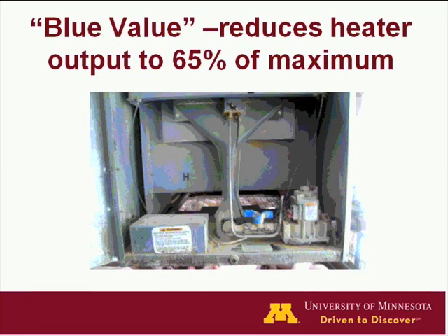It's generally accepted in pig facilities that most of the heaters are oversized. Most of the direct-fired heaters have a capacity of about 250,000 BTU per hour. You can buy heaters down to 60,000 BTU, but the difference in price is usually pretty small. So most producers end up getting these large heaters thinking, for only another $100 I can double my capacity.